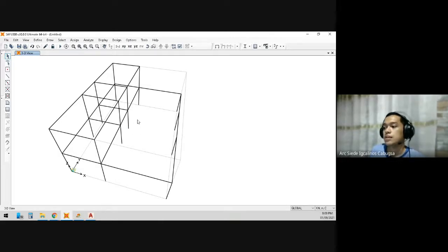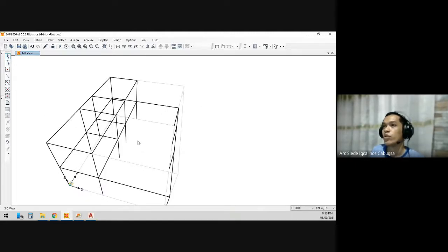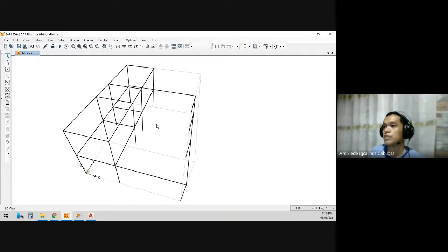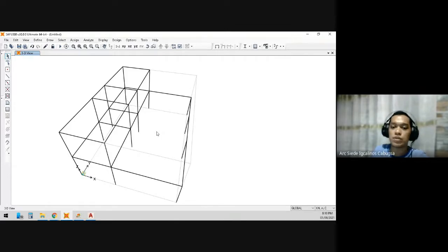model because I'm assuming that my tie beams are only used to tie the columns around, to prevent settlement, and it is not an element that resists force from loads coming from the building or from the other structural elements, but rather it is something that is there so that if ever your building settles, then it will settle uniformly.